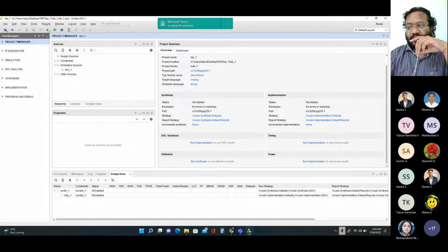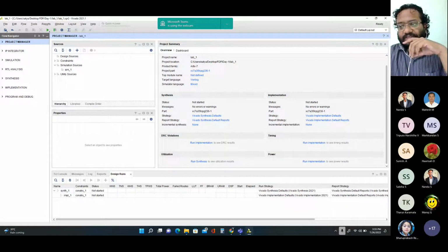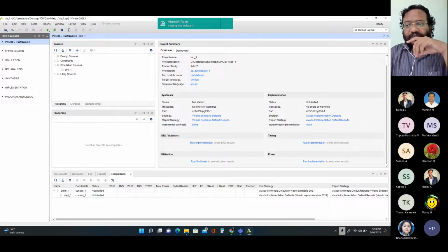If it is exceeding the clock period, then the timing is not met. So in that case, how do you achieve timing while operating at the same clock frequency? There are some specialized optimization methods, like pipelining and so on. You need to rework your architecture in order to reduce that critical path.